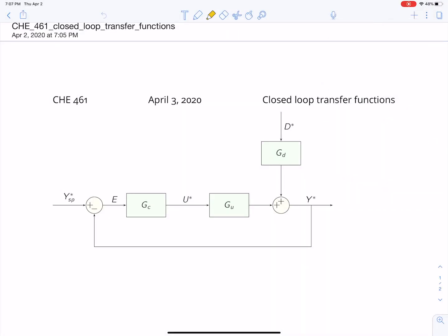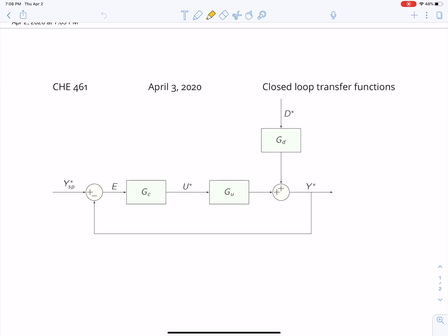Okay, in this module, we will talk about closed loop transfer functions where there's an input to a closed loop block diagram that arises from a process under feedback control. So this is feedback control because we have our controlled variable y. I'll label each of the variables here. And throughout this class, we will use y as the controlled variable.